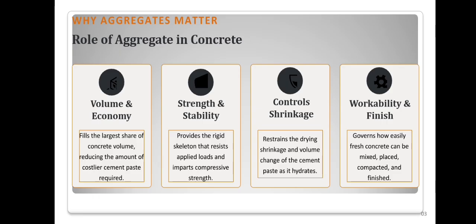Let us see why aggregates are so important. First, aggregates reduce the amount of cement paste required, making concrete more economical. Second, they provide a rigid framework that carries the compressive loads. Third, they reduce drying shrinkage and help control volume changes. Finally, they improve the workability of the fresh concrete, making it easier to mix, place, compact, and finish.